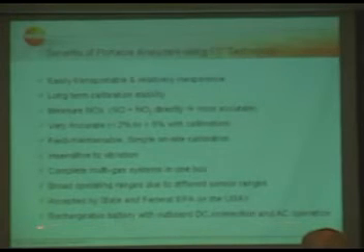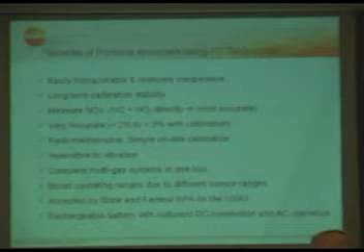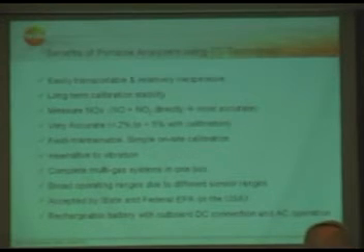One advantage of all portable analyzers using electrochemical sensors is a rechargeable battery with outboard DC connection and AC operation. That means because the electrochemical sensors don't consume that much power, we can provide a rechargeable battery. Depending on your application, where you measure very high at the stack where no AC power is available, you can operate the analyzers up to 4.5 hours without any AC power supply.